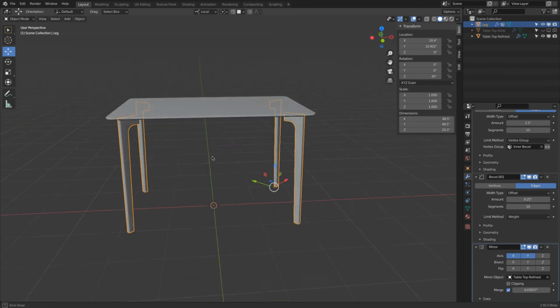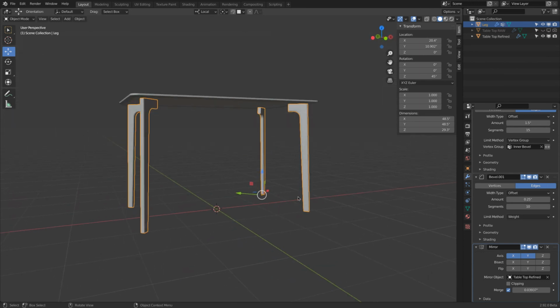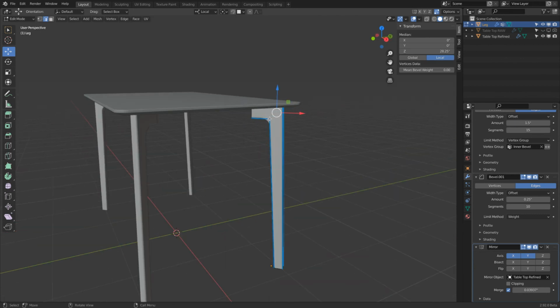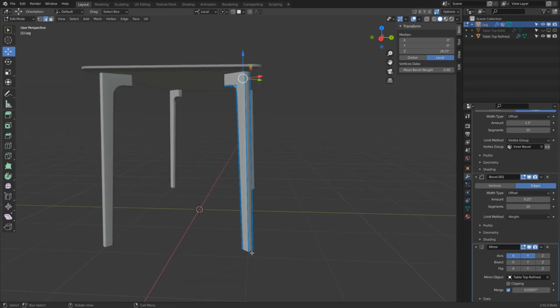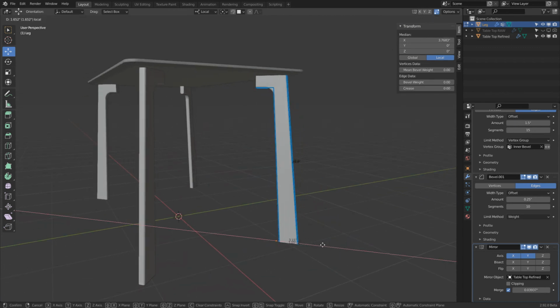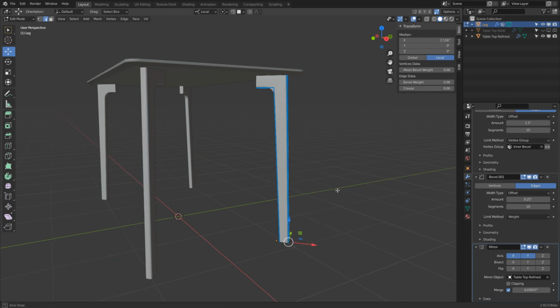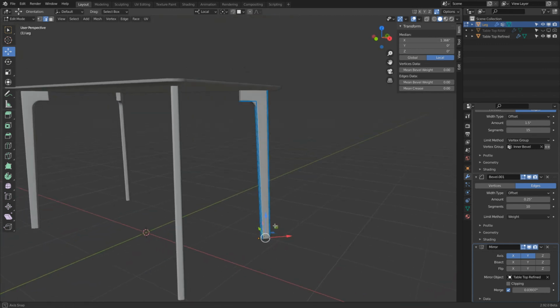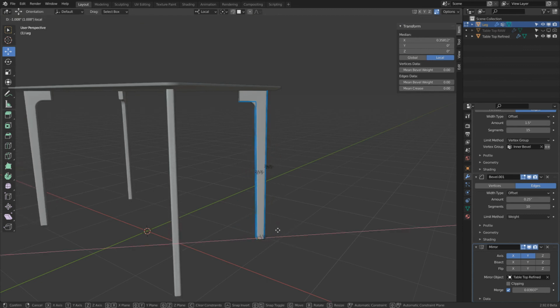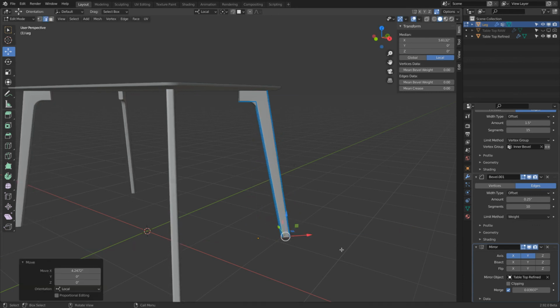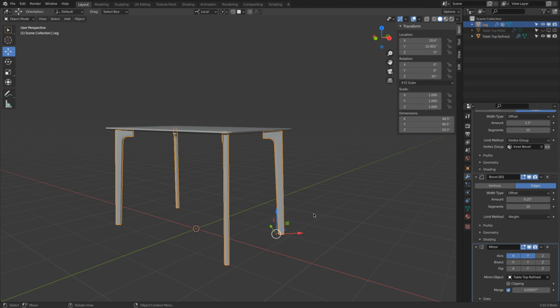And one interesting additional detail, because we have this line removed, and previously we moved also these edges up. When I move this, you see this just is a really nice straight line. So when I would like to change the angle, it's very easy to move just the bottom plate and all these other edges follow it. Okay, perfect. So with this we have finished our legs.